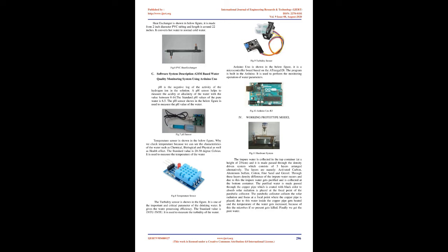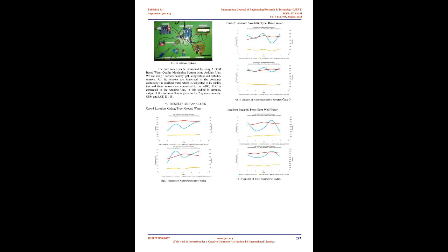Fig 3a shows the activated carbon layer. It is effective in removing the color, taste, and odor from the treated water. It is used to adsorb organic, chemical and mineral impurities present in the muddy water. Fig 3b shows the aluminum sulfate layer. It causes suspended impurities to coagulate into larger particles, and then they are filtered out. It is widely used as a flocculant to clarify the turbidity in water.